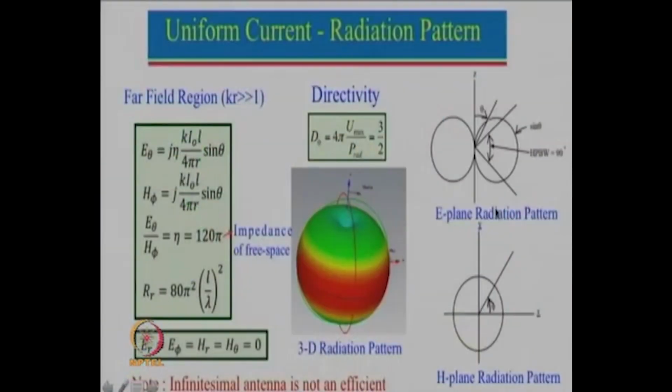For this dipole antenna, let us say we are standing here, we see the full length. Now, as we move along, and if we see from the top, all we really see is the tip of the pen. So we will see very little, and as we move along, we will start seeing a little more. In fact, the dipole radiation pattern is very similar to the way we look at this pen. The dipole pattern will be uniform along here, which will be maximum, and then it will go from maxima to 0, then again to 0, then to maxima. So, one can now see the pattern.